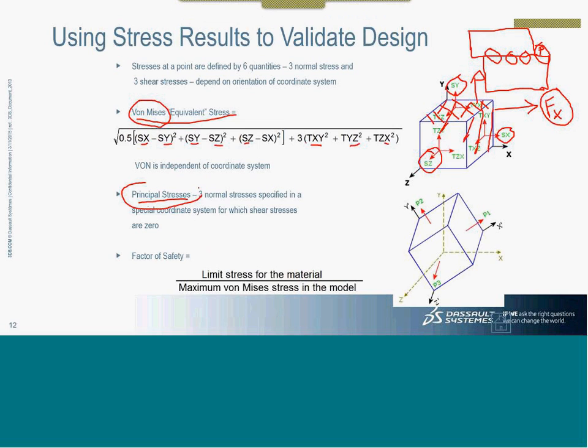If you see here, there is a particular thing called principal stresses. Typically, now I believe you are all comfortable with what you saw here. If not, please ask. And when I think of this bottom square, you can see that the same element or node or the cube seen for calculating the stresses can be twisted or rotated a little bit. It can be in such a way that we can reach a state wherein the shear stress, that is these stresses, can go to zero.